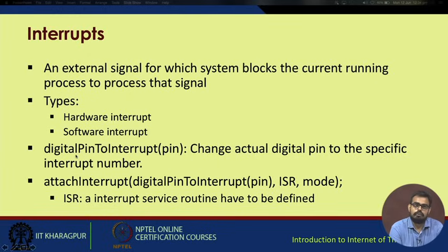As you can see, digitalPinToInterrupt and then the pin number. It actually changes the digital pin to the specific interrupt number. Then attachInterrupt, with digitalPinToInterrupt(pin), then ISR, then mode. ISR is basically known as an interrupt service routine. It has to be defined explicitly.